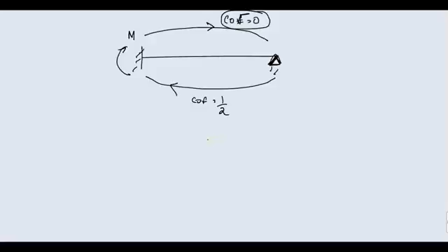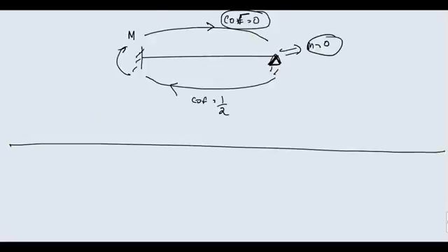Okay, so you have to remember, the carryover factor is 1 by 2 from this side to this side, but from the fixed to pin joint you have no carryover, because your pin joint cannot have any moment. So here the moment is obviously 0, so your carryover factor is also 0. Okay, so I hope you are able to understand. Now let's start with our method.